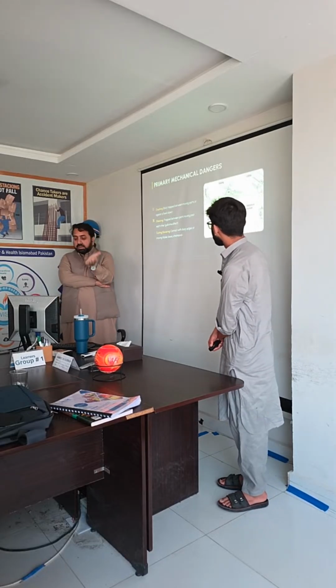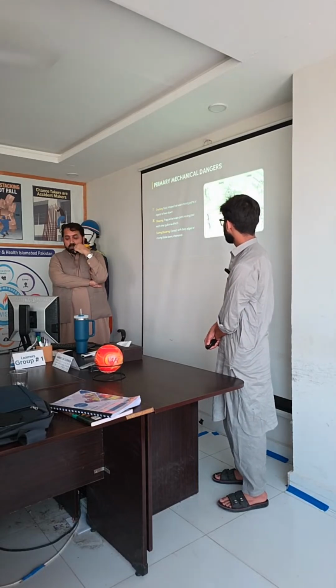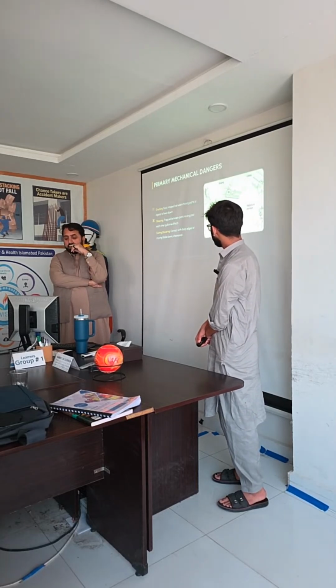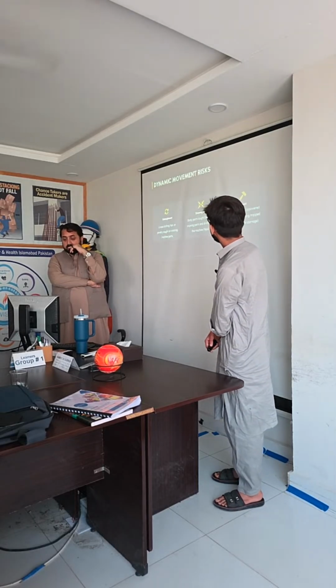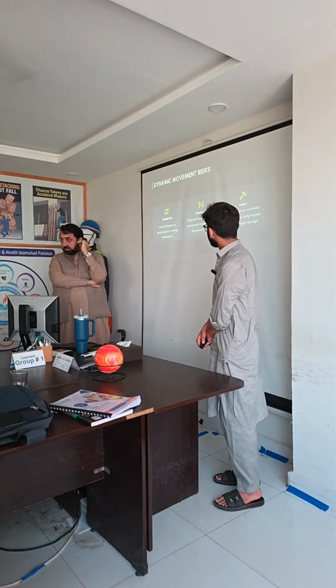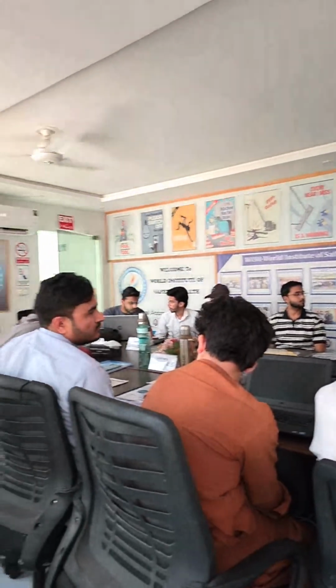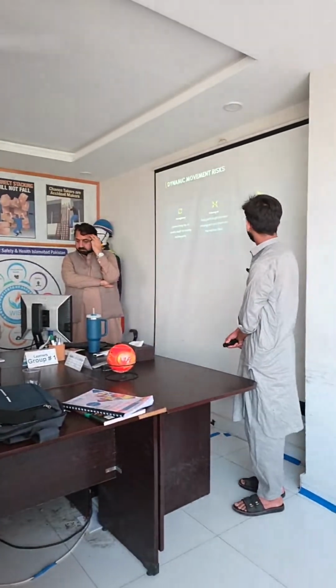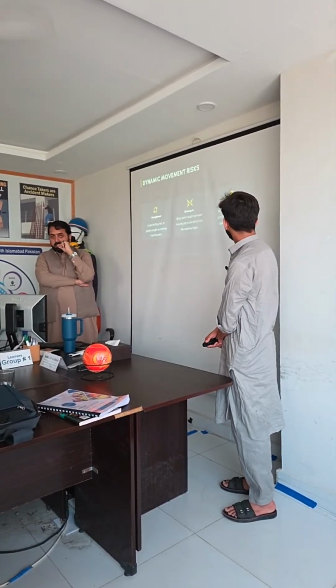hazards, which are crushing, shearing, cutting or severing, like I discussed before. Cutting: contact with sharp edges and moving blades. Dynamic movement risk. Entanglement: loose clothing, hair or jewelry caught on rotating machine parts. Drawing in: body parts caught between moving parts and drawn into the machine. Impact: body struck by a powered part without being trapped.